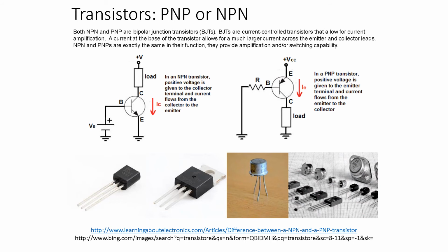So underneath at the bottom, you can see a couple different packages for transistors. Bottom left is the one that we'll use most likely in class. The one next to that, you'll see that there's essentially a slightly bigger package to it. The pins are a little bit thicker, and on the back you'll see a giant piece of aluminum, and that piece of aluminum is actually a heat sink, because transistors can get pretty hot, especially if we're getting into bigger, higher power ones like MOSFETs or whatnot. You need some way to cool them down, and so that big aluminum blocky part on the back helps. However, sometimes we will attach that to a much bigger heat sink, and that way we can really dump heat.